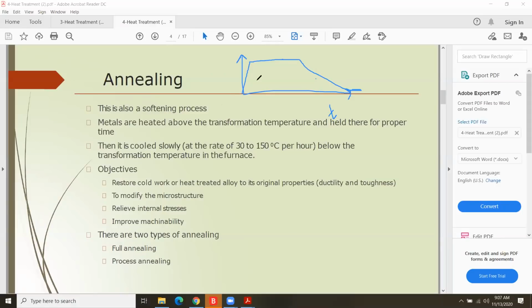So you are heating that metal to a specific range, so austenite is formed, right? Then you are holding that steel at this constant temperature. Why are you holding? To get a uniform particle or grain size, right?